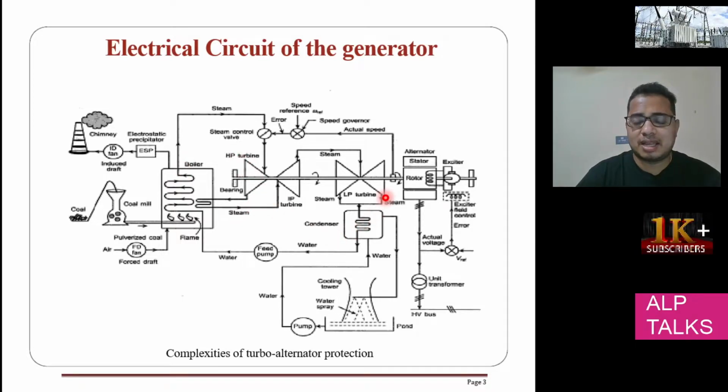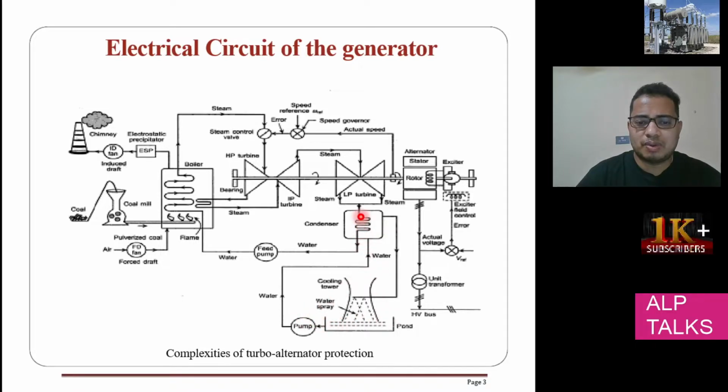Whatever the exhaust and final stream is there, the leftover steam, is going to be condensed, so we are going to use a cooling tower here. They will use water spray technology, and they will use one pump there, so it keeps on cooling and the water is reused again. So this is the generator setup.